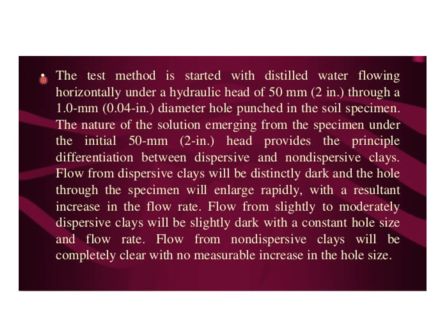The test method is started with distilled water flowing horizontally under a hydraulic head of 50 mm or 2 inches through a 1 mm diameter hole punched in the soil specimen. The nature of the solution emerging from the specimen under the initial 50 mm head provides the principal differentiation between dispersive and non-dispersive clays.